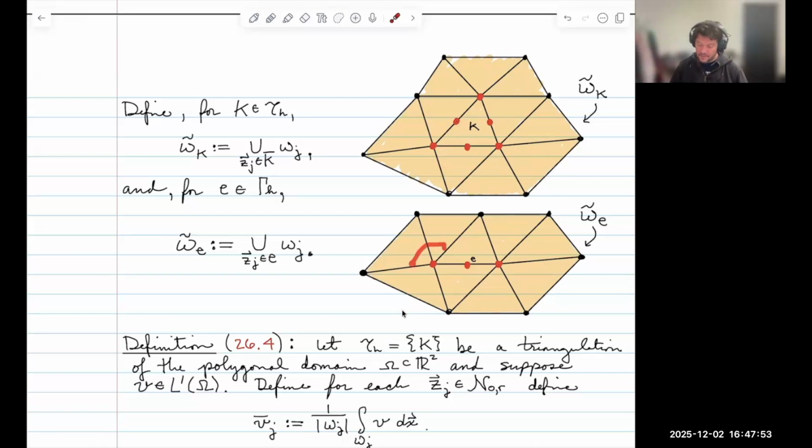So this basis function is going to have five triangles in its support, so throw that into the union. This one has two triangles, but of course those are already covered in this guy, so I don't really add anything there. And then I have this node here, and its support has these 6 elements. So I'm going to throw that in the union as well.